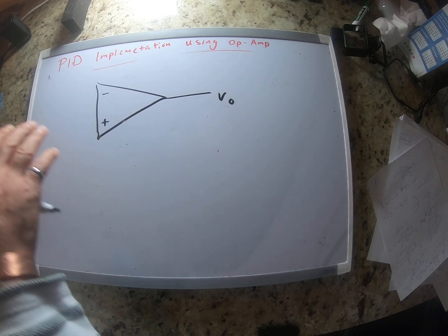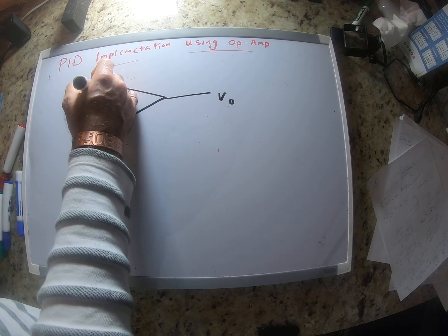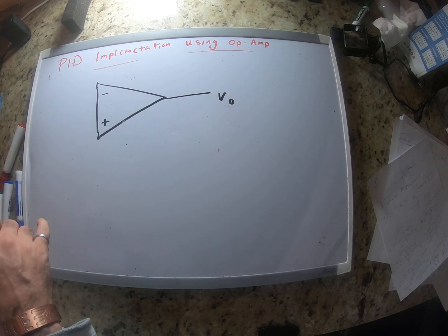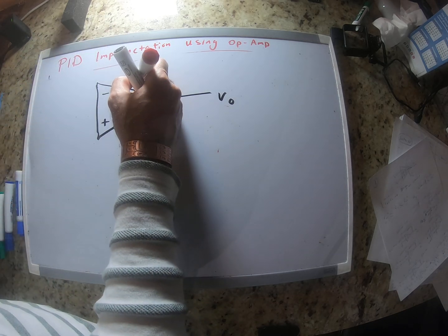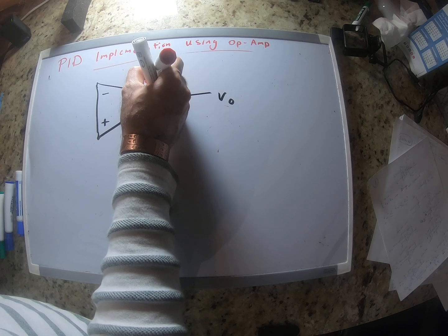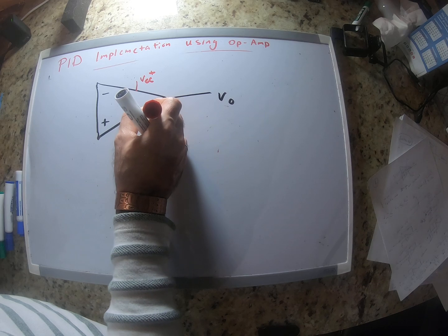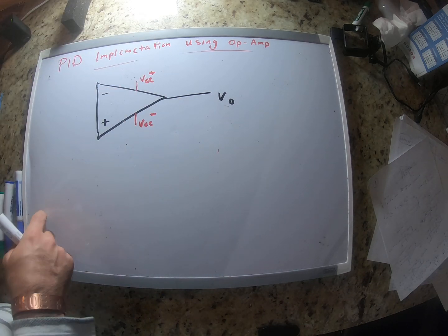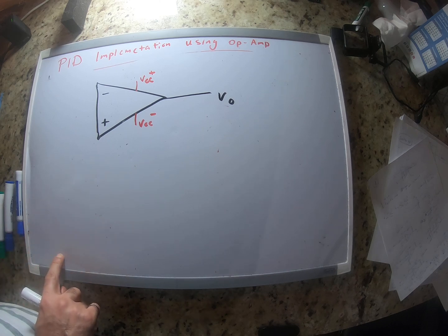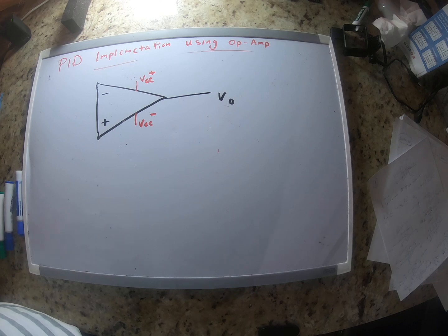But in the circuits that I'm showing you, we're using negative feedback, and if our input voltages are not that big, then output voltage is going to be within the power supply voltages. So all the two rules that I mentioned, VP equal to Vn, and In equal to 0, those are valid.